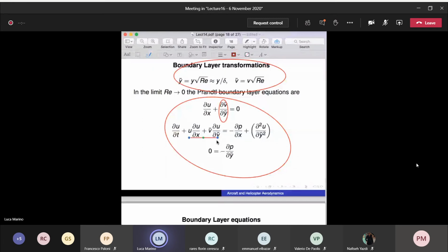So you can ask, where are the boundary layer equations simpler? Apart from the fact that we can neglect pressure, because it is something that we know, the other simplification with respect to the full Navier-Stokes equation is that, missing this term, it is possible to have a universal solution.